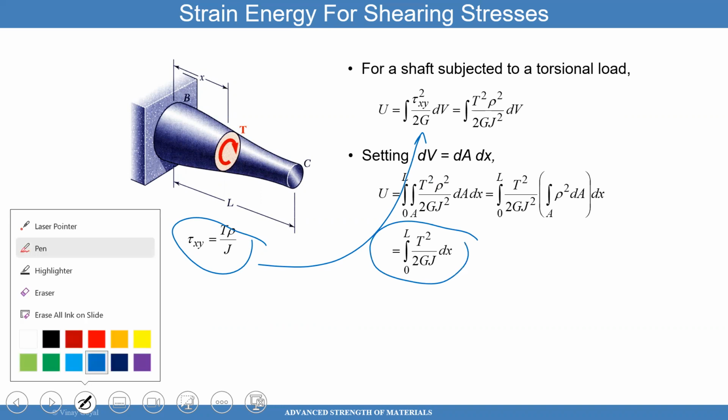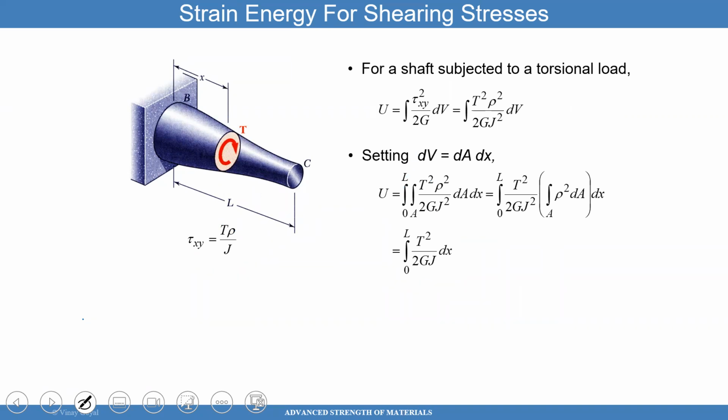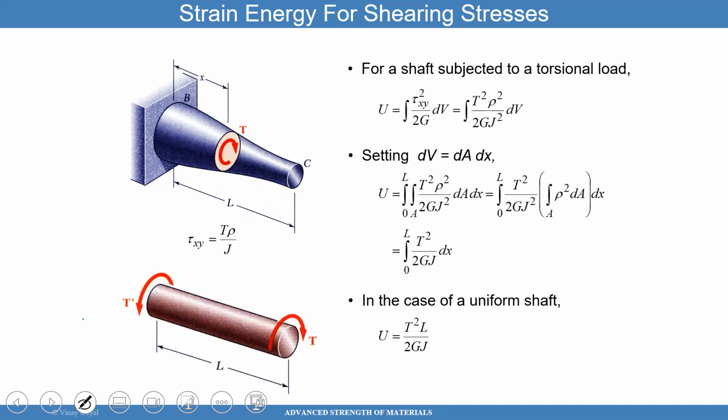So for bending is what I had shown in the previous page, but now when you apply torsion, it's torsion squared. G is a shear modulus. J is a polar moment of inertia. And if I apply a torsional load for something that's length L, just uniform, the strain energy becomes that. Make sense? I can do the same thing where I equate this to 1/2 torsion times phi, how much rotation you get from the load application. But I won't do it here. I'll cover it coming up. Any questions you have on what I've done here, please?